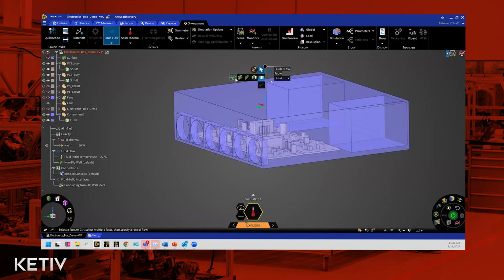You don't necessarily have to go with the fan intake boundary condition. You could retain the blade surfaces and then create an MRF zone around it, just like you would in others' flagship CFD problems. For the sake of time, I'm choosing the simplest option right now. So let's go ahead and choose a fan boundary condition.